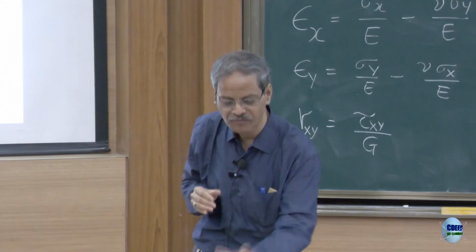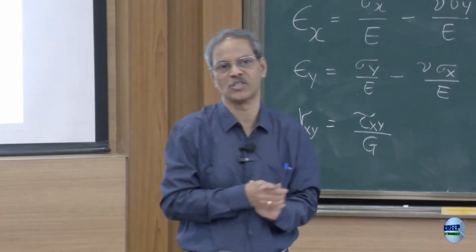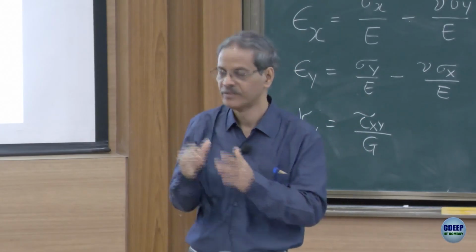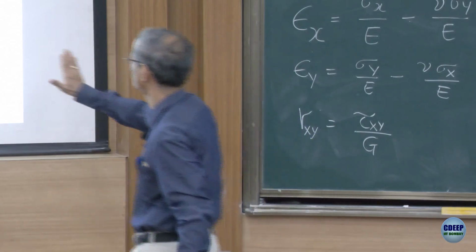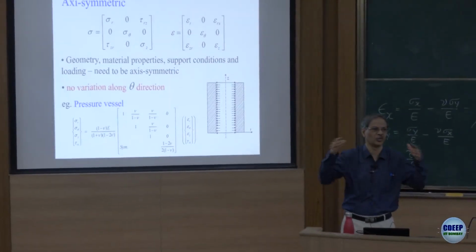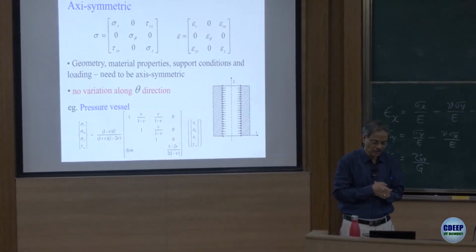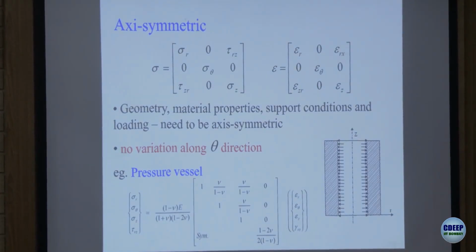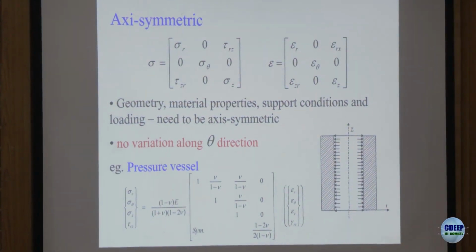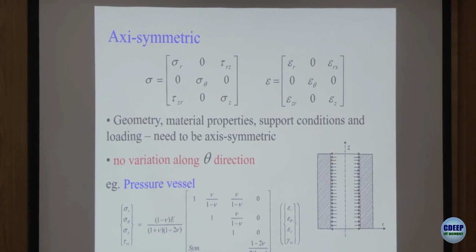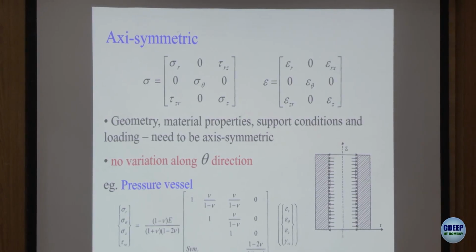Now coming back to this, if everything is cooperating with you and you are able to make an axisymmetric analysis assumption, then you would take only one plane like this, RZ plane, because around that theta 0 to 2 pi is all constant, so you don't have to worry about it. So again, it is a two-dimensional domain for finite element analysis. But the interesting point you have to understand here is, like earlier two-dimensional things, it has sigma r and sigma z. Okay, sigma r, sigma z, yes.